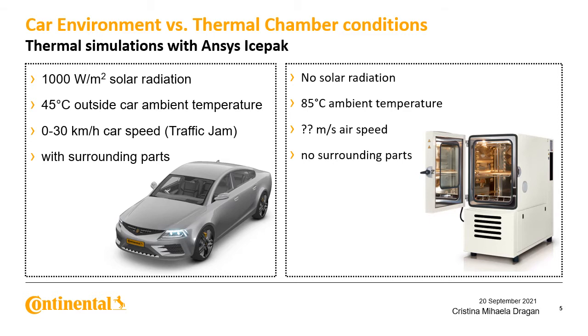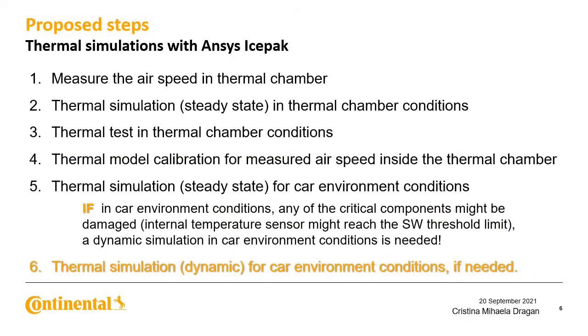But we have to be aware that tests in car environment conditions are quite expensive. So, I ask myself, what can we do in order to increase the confidence level of the thermal simulation and decrease the cost for measurements? As the first step, I propose to measure the airspeed inside the thermal chamber planned to be used.